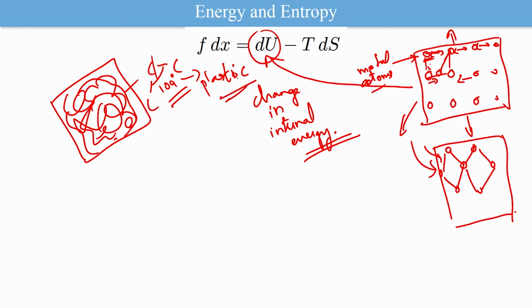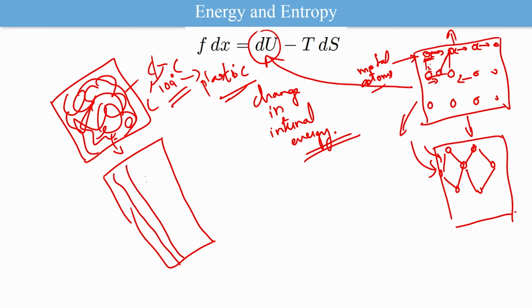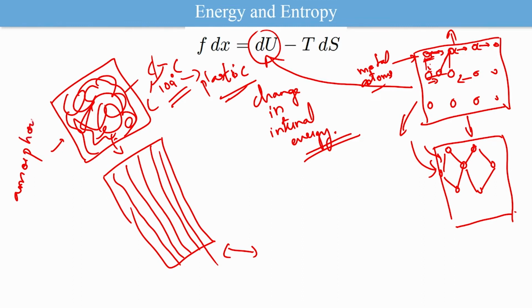Okay. So, in most cases what happens is this: if you stretch the rubber, the coiling of the monomers that you have seen here will stretch out to become straight. Okay. That is the change that actually happens in rubber, and when you leave it, this state can be referred to as the amorphous state, and here it is more like a crystalline state.